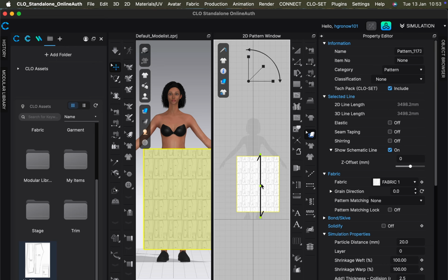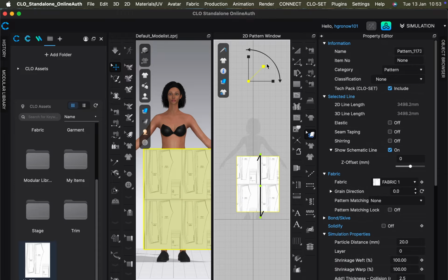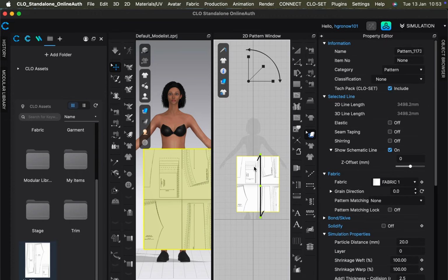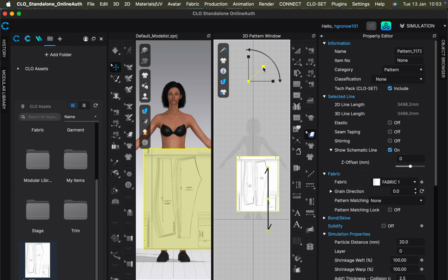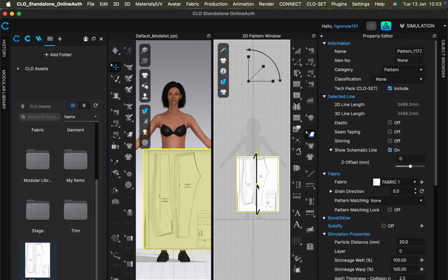Now we need to resize this scan so it's all in line with the size of the avatar. Click on the texture button. It looks like a fabric swatch folded over. Click back on your rectangle to select it and then resize. Pull the line out that is in the right corner of your 2D window. You can click on the rectangle to reposition the pattern and resize until you're happy with it. You can also see the size altering in the 3D window.